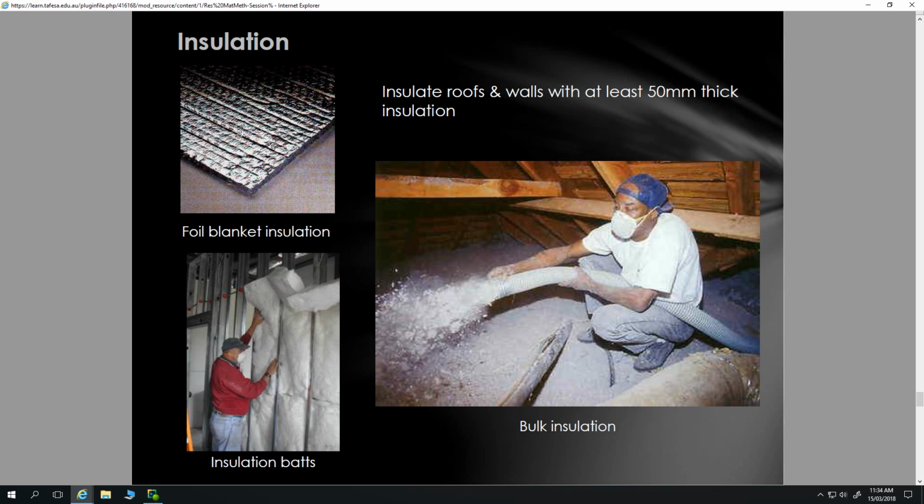But how do you go then with downlights and exhaust fans and stuff like that? Well, yes, then you have issues with those. So for an exhaust fan, you'd want a shroud around that, so you've got space around your exhaust fan. Downlights, yes, not sure how you work with downlights in that scenario. Because with the old downlights, the ones that aren't LED, they would just burn up there. Yes, it has fire retardant in it, but that would certainly make me incredibly nervous.